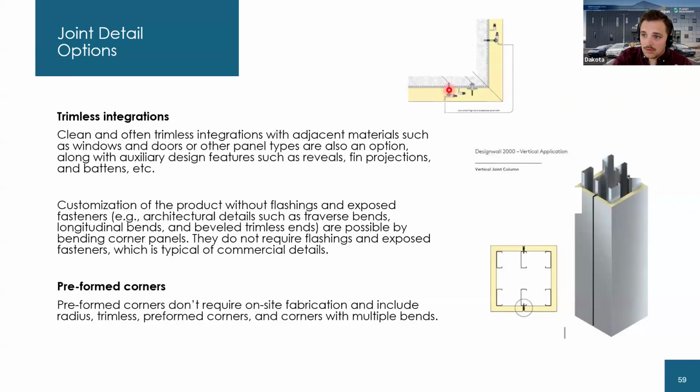And we can wrap that corner while still getting that nice insulation on insulation contact and dealing with the corner that way. We will have to adjust the legs of our IMP, essentially the length that wraps around that corner, to where it makes sense. We can tie into another IMP if we don't want a joint. Otherwise, we could see some trim there. But essentially, we can solve a corner without ever having to worry about trim or extrusion or something like that. So again, people overlook this, but just know that technology already exists. We can do that.